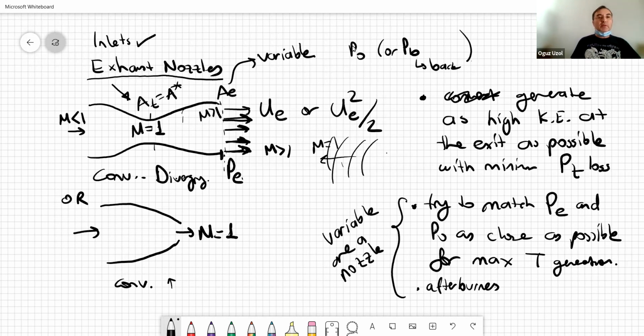But that's the case for passenger aircraft. That's the case for cruise flight, for fighter aircraft. But for maneuvering, strange maneuvering cases, dogfights and whatever, then lift can be lost totally. If you have thrust vectoring capability, you don't crash to the ground. It's already coded into the flight control system, and the aircraft takes care of that.